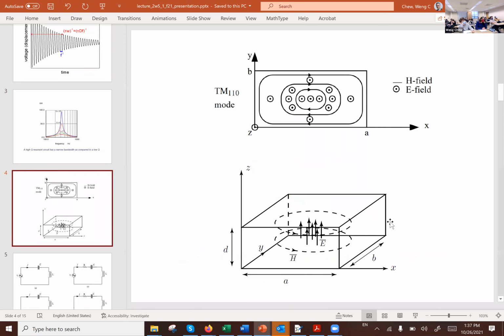So if you have a cavity, such as a rectangular waveguide cavity, which is the easiest one to solve, all of you know how to solve for the solution of this thing. And you actually can find a Q of this cavity in somewhat closed form by looking for places where the energy can dissipate.